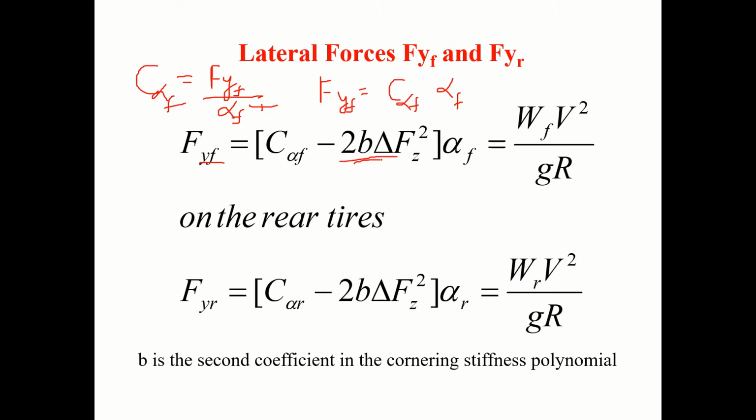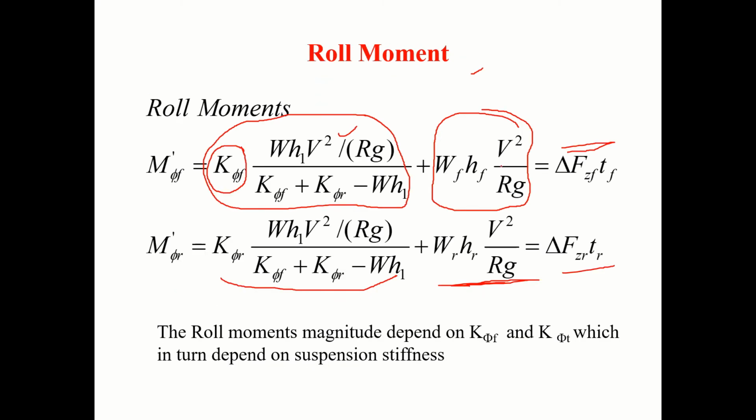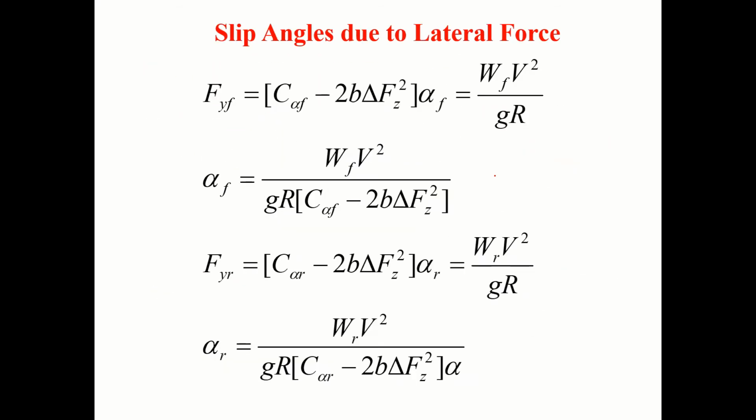So this lateral force, the tire grip force or lateral force at the tire, must be equal to centrifugal force. Same way on the rear side, I can write like this. Is that okay? So now we have got some interesting relationships. You see here. From this equation, let me get alpha F. From the second equation, I'll get alpha R.